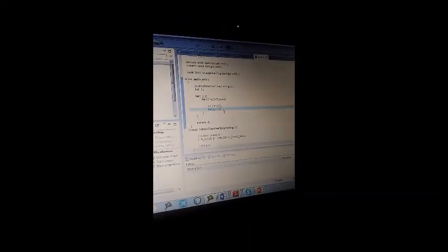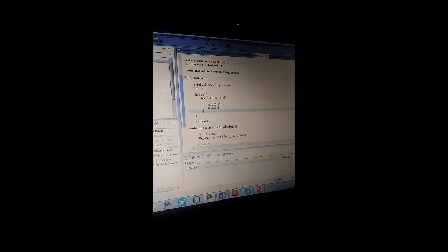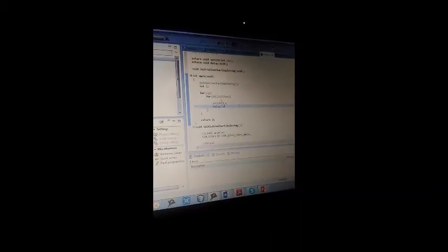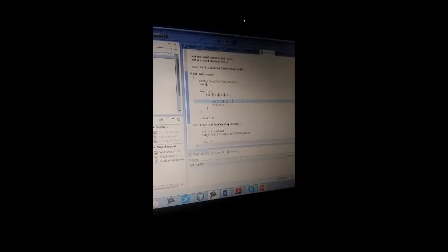So how does the function work? It's actually here. We will have an infinite loop, and within that loop, we check through from the reading of 1 to reading of 6. As my friend mentioned just now, we will pass the I into the setLED function, which is the extern void setLED. By checking the condition, whether it is 1, 2, 3 or up to 6, we will set the correct LED to light up. After each lighting up, we set a delay of 1 second by using the algorithm just explained by my friend. With this, we will make sure that the LED lights up every second.